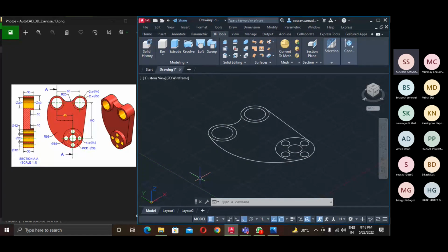You can use the subtract command and also the extrude command, both with the command called press pull. If you press something, then the function of subtract will work. And if you pull something, then the function of extrude will work. So what you need is a closed region.